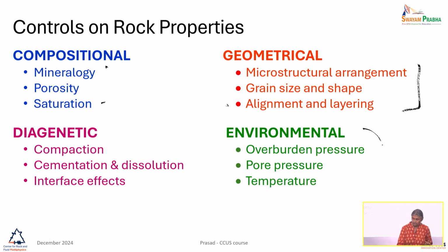And then we have environmental changes: pressure, temperature, fluid pressure, overburden pressure, pore pressure. Because we are dealing with carbon dioxide, this part becomes really interesting because we have phase changes going on. And so we are usually trying to be in one phase, in supercritical phase most of the time, for the depth and temperature gradient that we select.